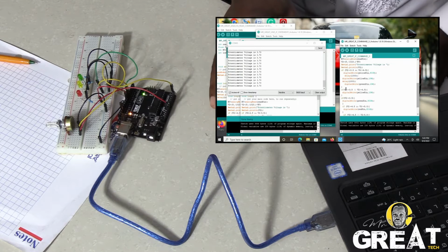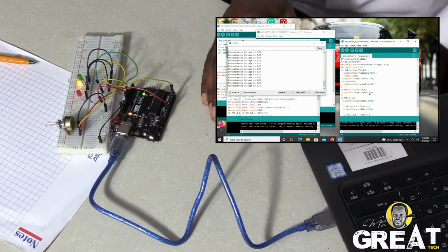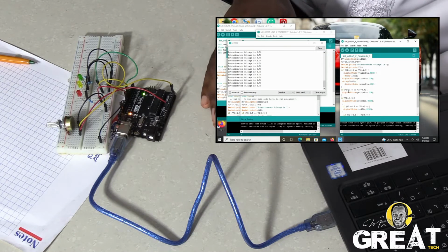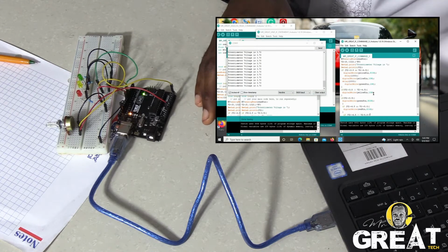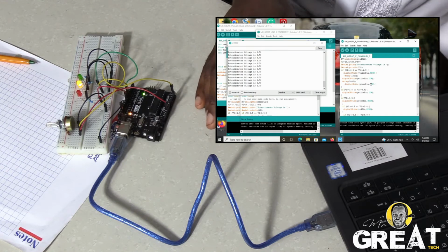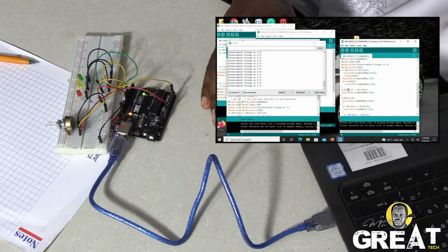And when is yellow going to turn low? Digital write yellow pin low, if this is the only command binding the yellow pin, which is the yellow LED on pin 7. So digital write pin 7. Which is the yellow pin, sorry. Now this is the command binding it, this is the if command.